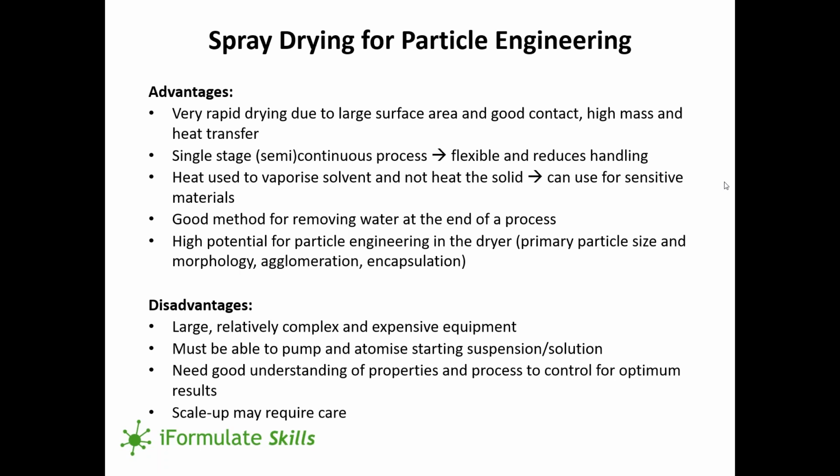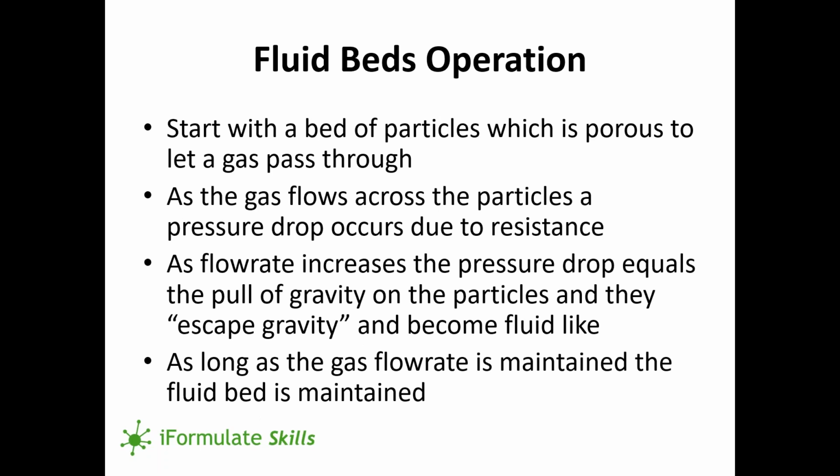Thanks, Jim. Fluidized beds and spray dryers have things in common, in the sense that you're dealing with surfaces of particles or droplets, which are very small, and consequently you can get a very high surface area to volume ratio, which allows you to do lots of things more efficiently, because you can have high heat and mass transfer coefficients.